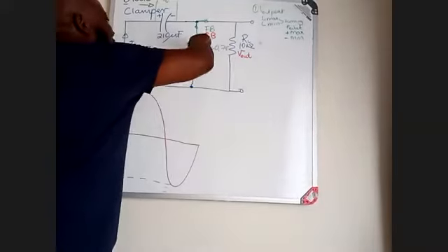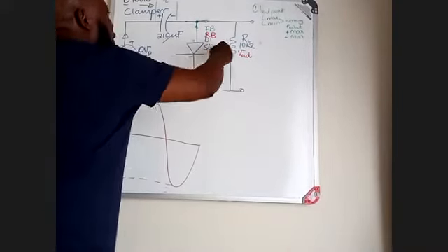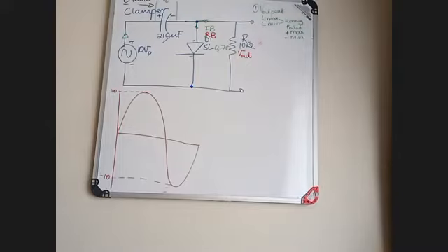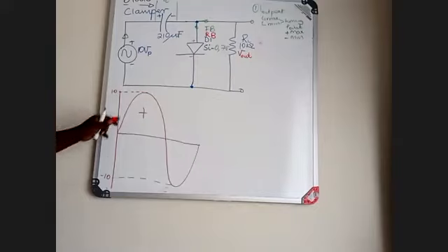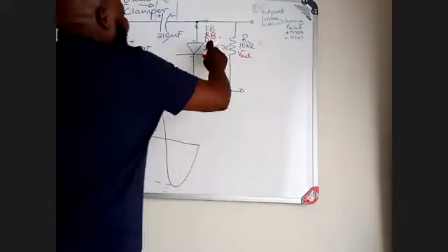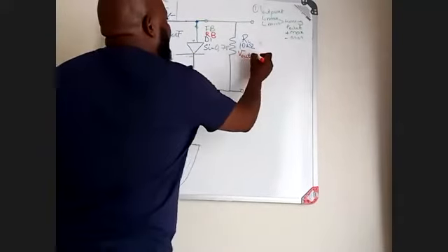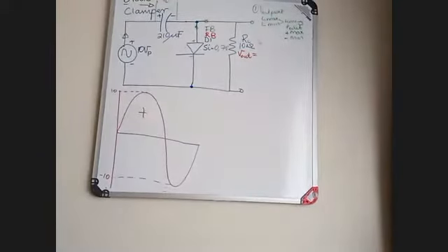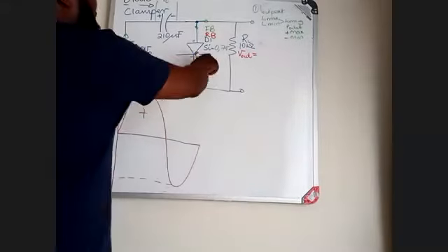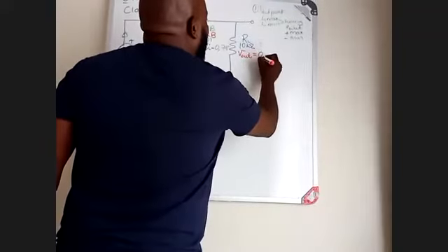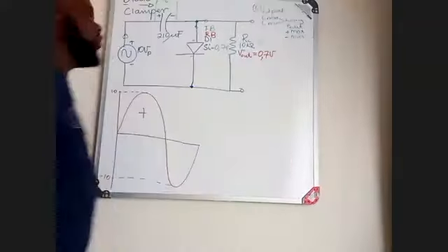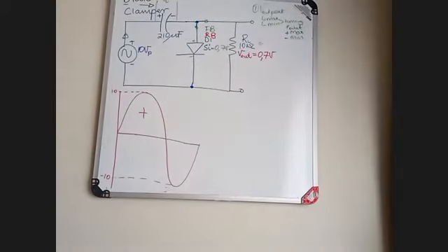Now, when this one is switched on, which means it's forward bias, then 0.7 volts has been established. But during when? During the positive cycle. Once this is switched on, what is the voltage that I'm going to measure there? I am going to measure 0.7 volt. During forward bias, I have measured 0.7 volt.